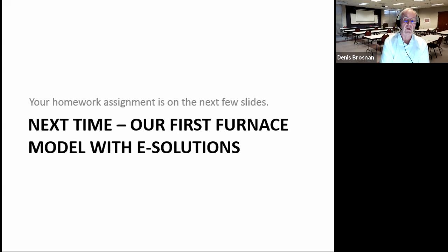This has been a fairly long class today to cover this subject. I've talked a bit about safety features, freezing of castables, and explosive spalling of castables when they appeared to be set but weren't. They were frozen or weren't in good condition when the dry-out happened in the furnace environment.